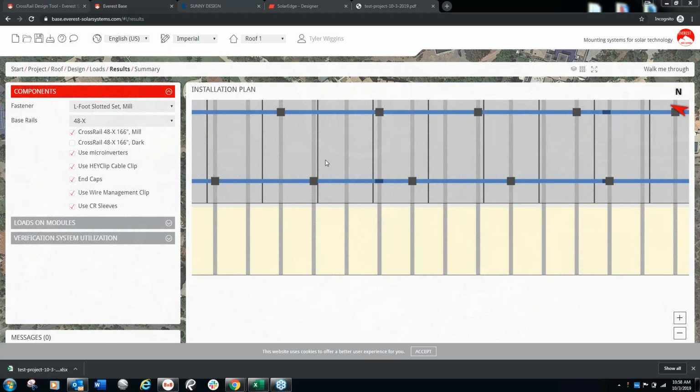They have a lot of information on installing those fasteners into concrete. If you're talking about sloped roof systems, I kind of covered that before. I definitely recommend choosing a slotted L-foot and then making sure that the particular anchor you're choosing is compatible with that concrete roof, as well as compatible with that L-foot. So hopefully that answers that, but again, please feel free to ask a follow-up.